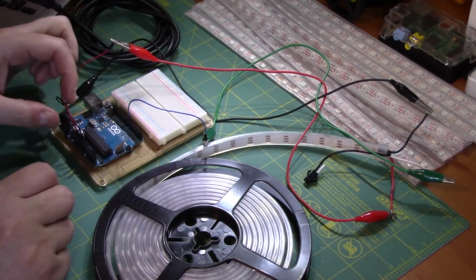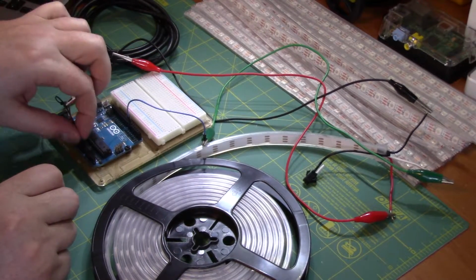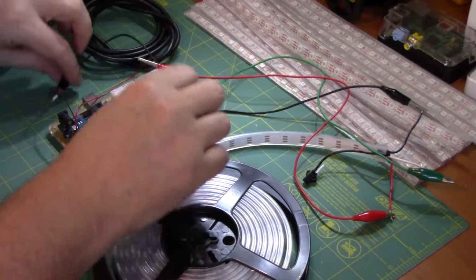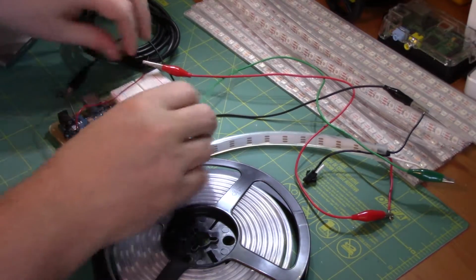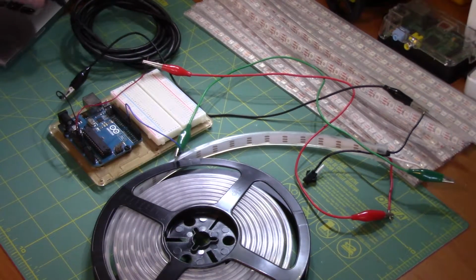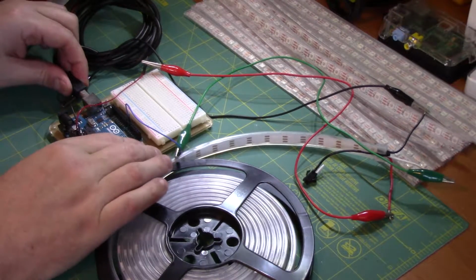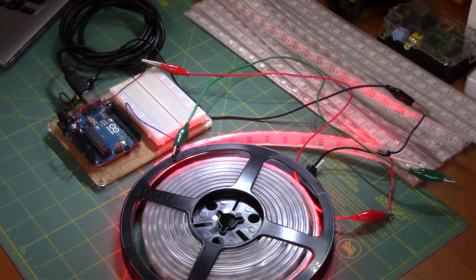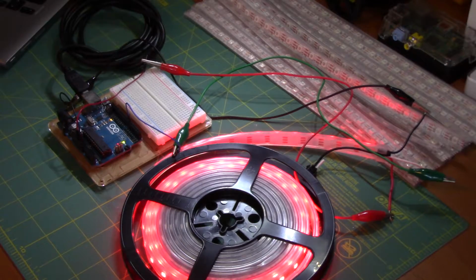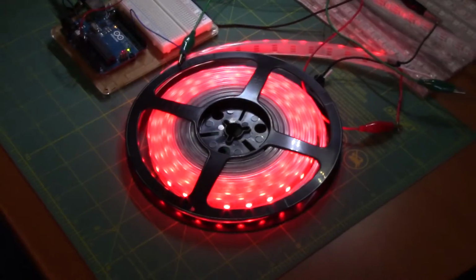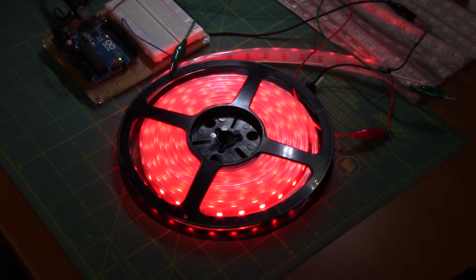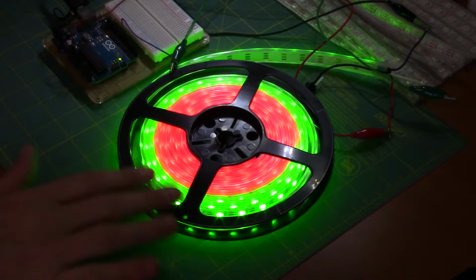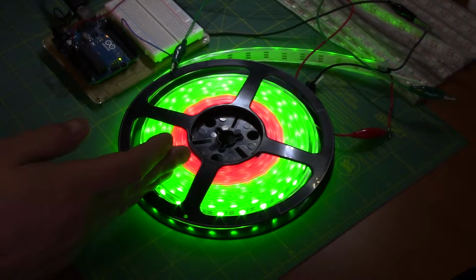And you can really use either the 5-volt or the 3.3. Both will work for these NeoPixels. And then make sure your alligator clips aren't touching each other or anything else on the board. Keep everything separate. And then once that's done, plug in power to your board either from the computer or from an external battery. And once it powers up, your LEDs start going. You can see it starts out doing the red sweep, and then it'll do green and then blue. And this is a good way to test to see if there's any individual pixels not working, or if the strand cuts off at some point.